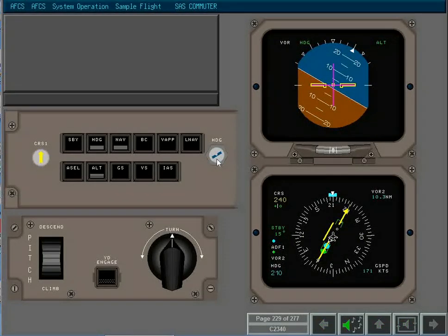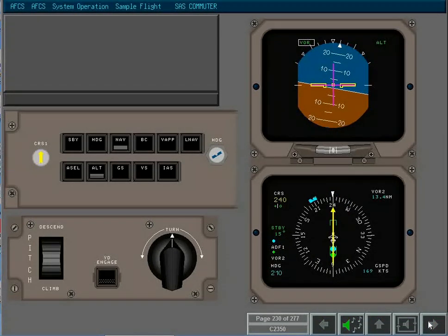The autopilot rolls the aircraft to the selected heading. Bank angle depends on displacement between the heading bug and the aircraft nose. AFCS moves from heading to nav and rolls the aircraft onto the selected heading. The capture phase is enunciated by the boxed VOR mode, and the aircraft tracks the selected radial. As a point of good airmanship, you should put the heading bug on the selected course.